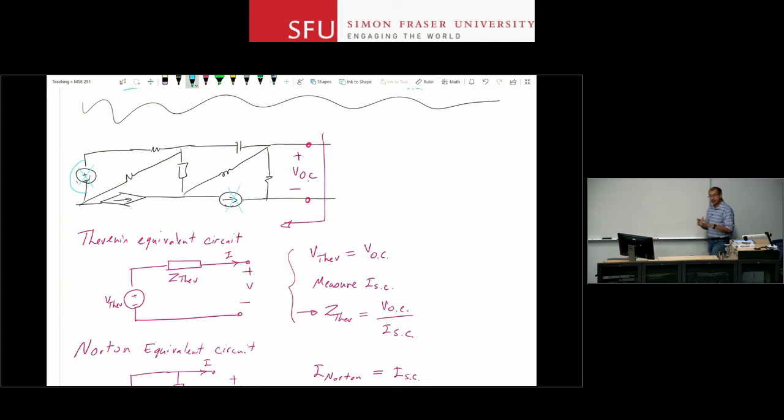I keep all the dependent voltage or current sources that I may have in that circuit. So all the independent ones are gone. All the dependent ones stay. Then I attach a test source to the port here. So let's just call this Vx. You can use a current source. It's your source. You can use a voltage source or a current source, whichever is more comfortable in different circuits. Sometimes it might be easier to use a current source. And I attach a test source. Some people use the value of 1 for this test source. I just say, use Vx. And then you calculate Ix.